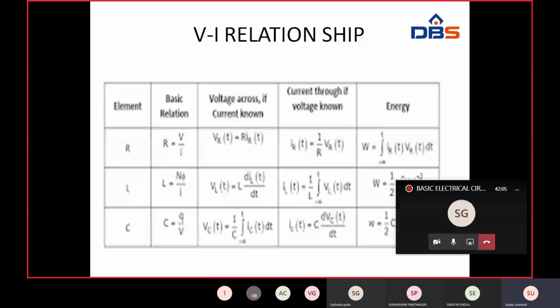Next, plus to minus, minus means drop of potential, I into R3. Next comes plus to minus, minus of I into R4. Next here I am telling that this is plus and this is minus. Plus to minus, minus I into R5. Minus to plus, plus V, rise of potential, plus V4 is equal to 0. So we start at V1 and we end at V4.